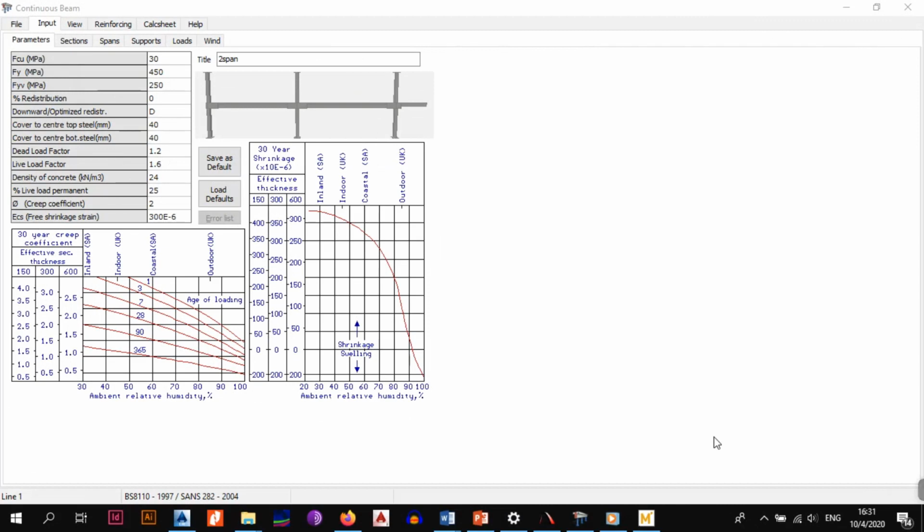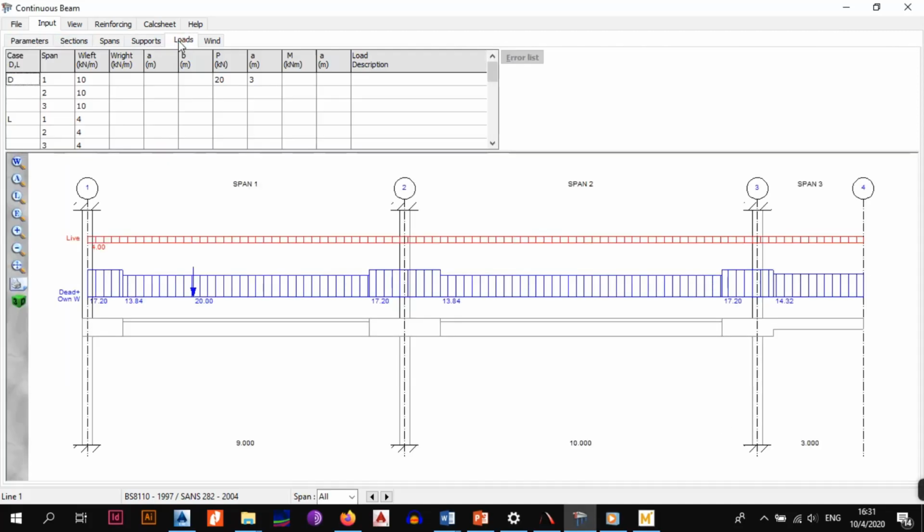Alright, like I told you in the introduction, today we're looking at the beams, and obviously most of you are thinking, okay, this is how we design beams in Prokon. Yes, this is how we're going to be designing all of our beams in Prokon. But first of all, you see this tab called loads is a very important tab because this is what defines whether you have done a good analysis or a good design. I know it is the fifth tab, the last thing that we need to worry about before we actually analyze and design our beams.